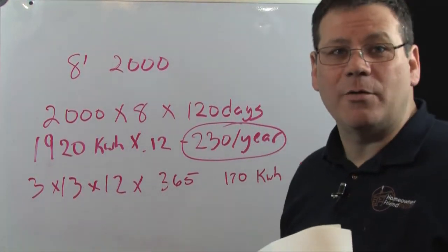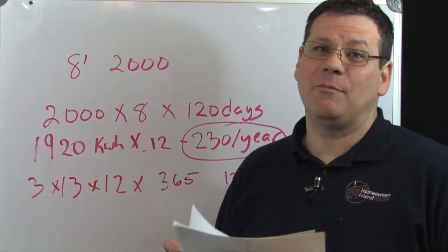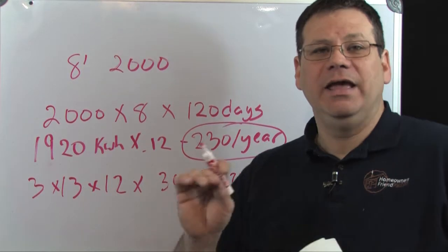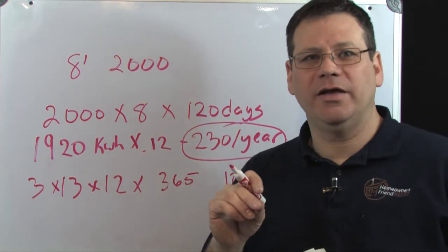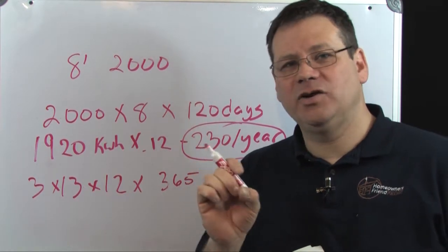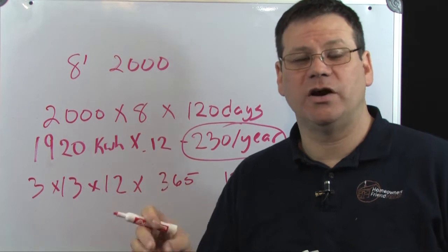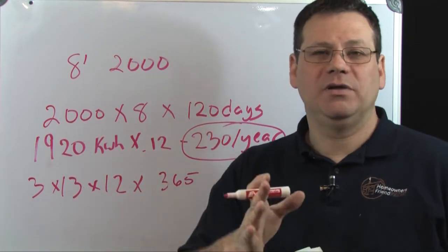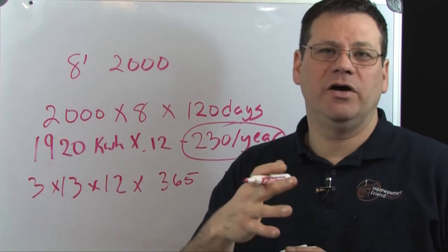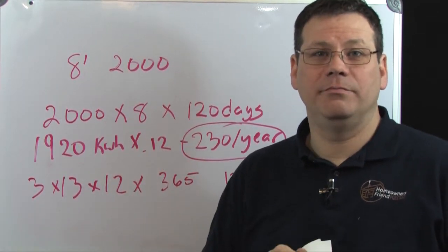Now, 12 cents a kilowatt hour is pretty cheap for power. Where you live, it may be a lot more expensive, and you really got to check that. And the other thing, I'll talk to you a little bit later about calculating the cost of power, but on your electric bill, it's not only the cost of the power. In a lot of areas, there's a generation charge, which is actually the cost of the power, but there may also be a transmission charge or other charges on the bill. So you need to look and figure that out completely.